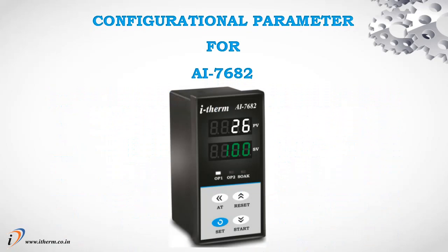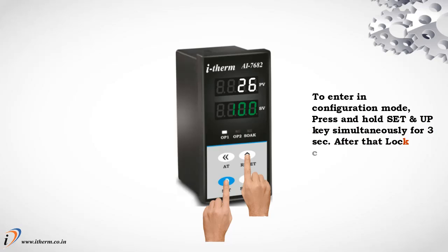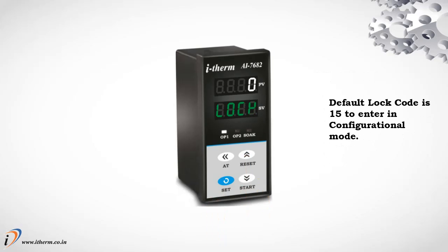Configuration parameters for AI7682. To enter configuration mode, press and hold the Set and Up keys simultaneously for 3 seconds. After that, the lock code will appear. The default lock code is 15 to enter configuration mode.